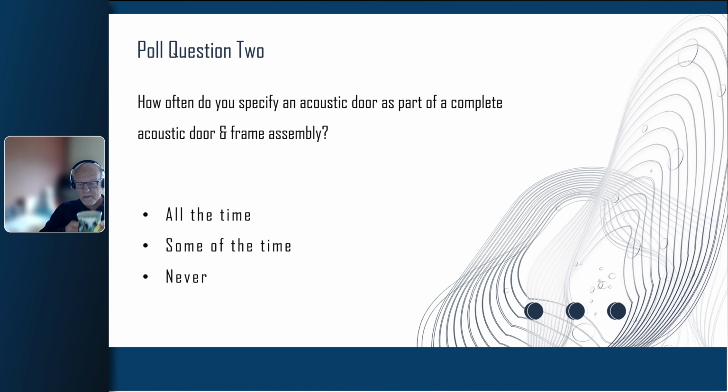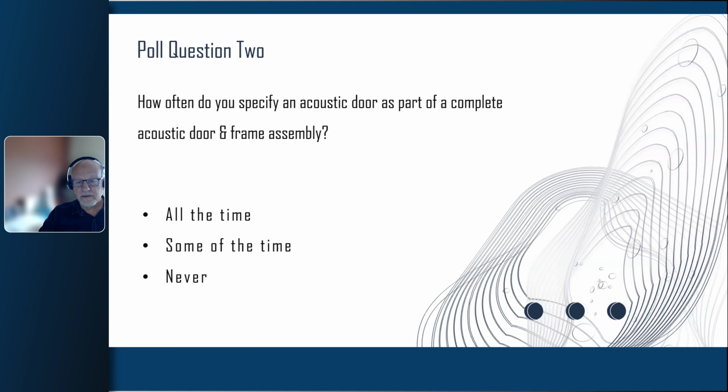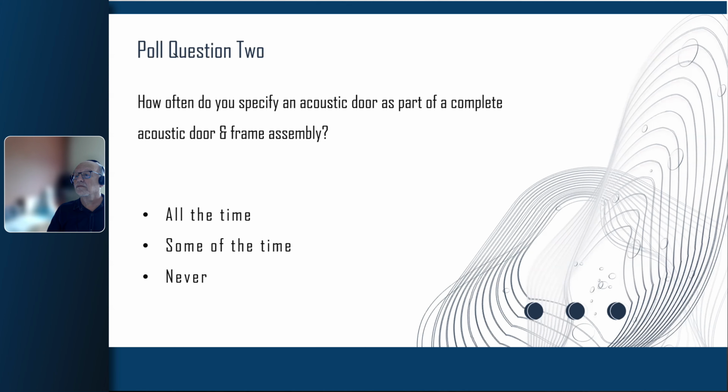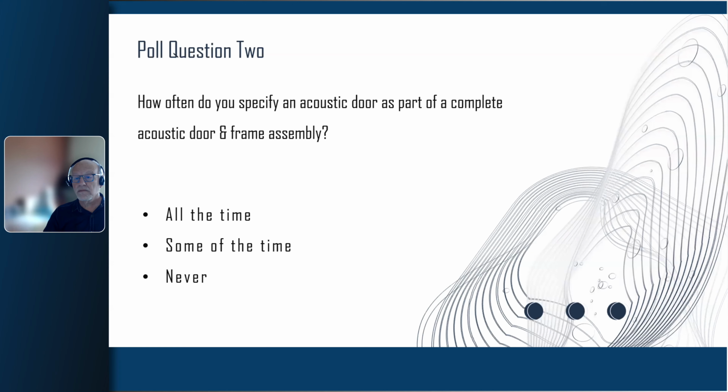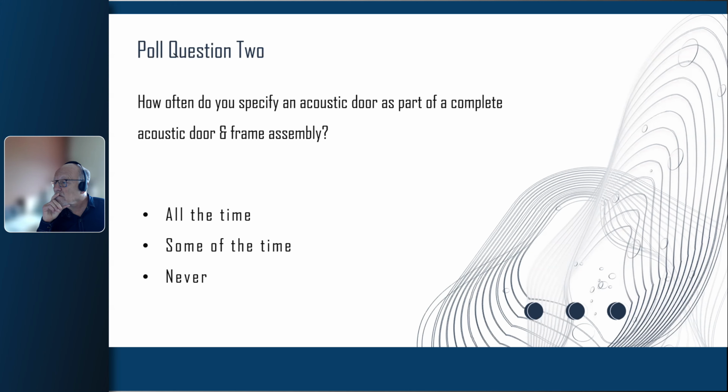And in the meantime, Jack, this is the follow up to Maria's question earlier. Maria's asking, would you go 1-to-1, meaning specify STC 50 and require NIC 50? That's a good question. They're measuring different things. The STC 50 is measuring what we did in the lab, whereas the NIC is measuring what the result is in the field.